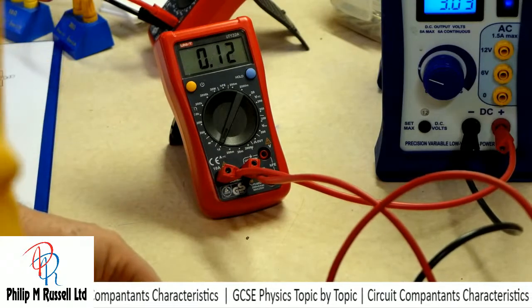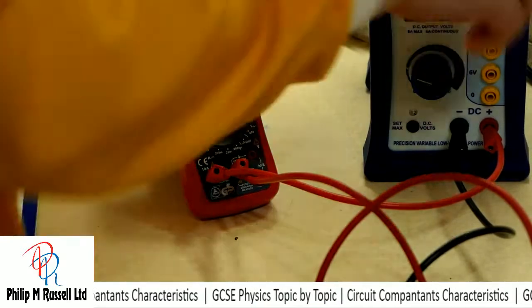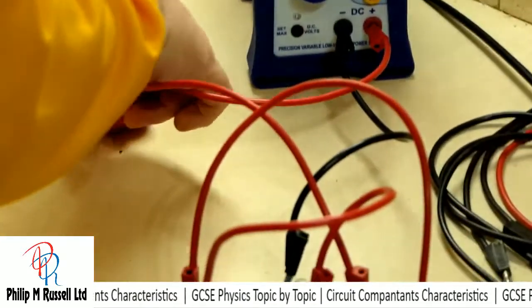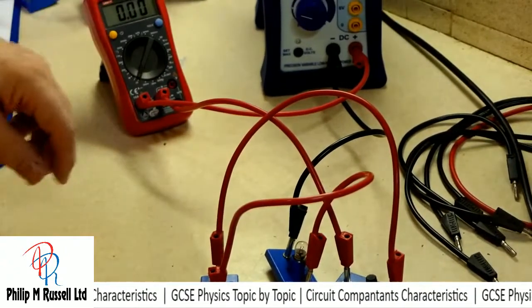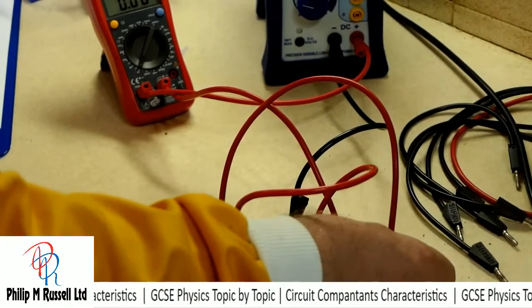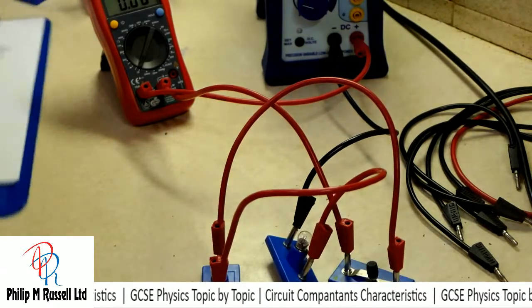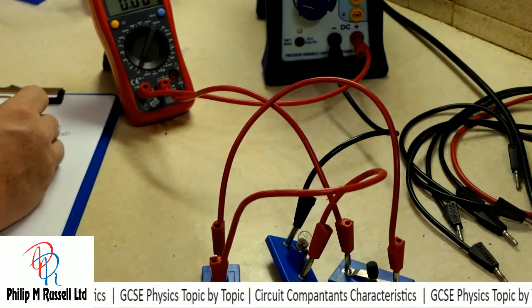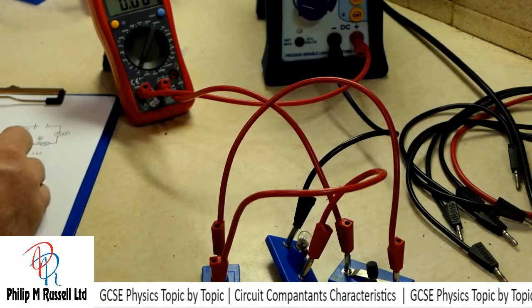The only problem with this wiring is, you can see my bulbs are now very much dimmer. Let's just make sure I've got a good connector. No, my bulb's still dimmer and it's 0.12. So it looks like I've got a very bad connection somewhere in my equipment, causing me problems today.